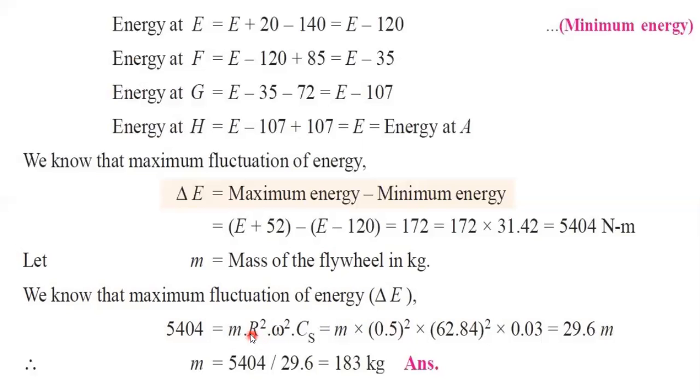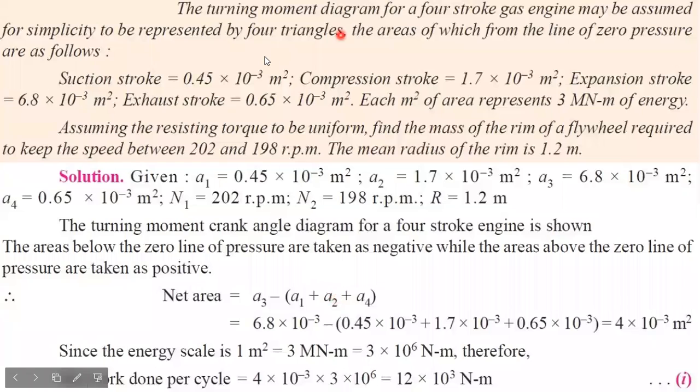This case is possible and applicable only for the flywheel rim alone. So in mr², the r value we know, the ω value we know, and the Cs value we know. Only m is the unknown. So keep m alone on one side and take everything to the right hand side, and you will get an answer of 183 kg. In the next problem...